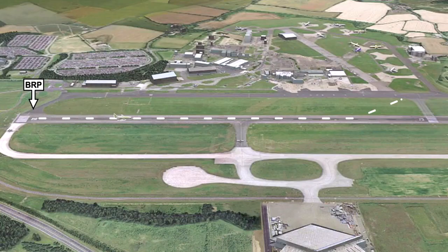The takeoff stage of flight is defined as being from brake release until the aircraft reaches a specified height, called a screen height. The screen height varies from 50 feet for Class B aeroplanes to 35 feet for Class A aeroplanes. As the aircraft accelerates down the runway, a speed will be reached where the pilot applies back pressure on the control column to raise the nose wheel off the ground. This procedure is called rotation, and it is initiated at an indicated airspeed which is called VR.